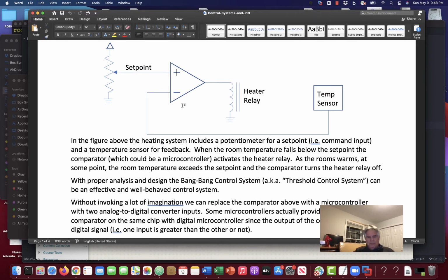So with an analog system, you'd have to do that with potentiometers and that sort of thing, and they used to do that, and they'd put some kind of this Loctite, used to make, still does I guess, this goop that you could put on trim pots to do two things. One, keep dirt out of the trim pot, hopefully, and number two, just put an added kind of stickiness there so that the trim pot didn't change in value over time.